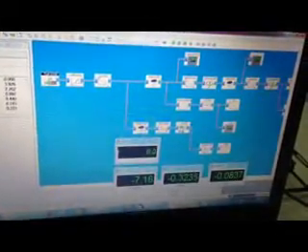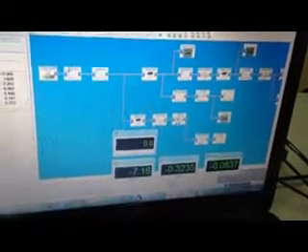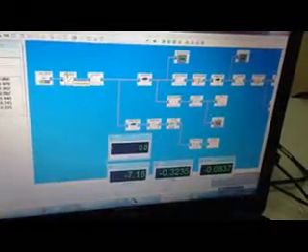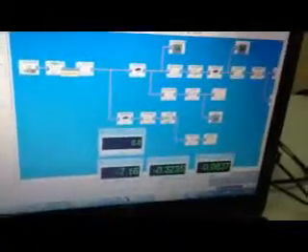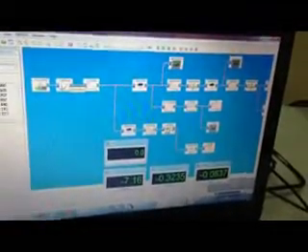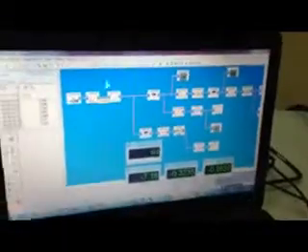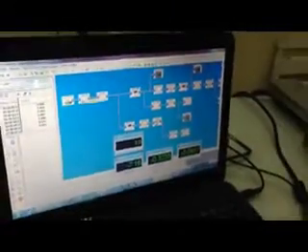Then in this lab, we need to do calibration. This calibration is to convert voltage into displacement. So we do the calculation by some experiment, and then we get the y-intercept and slope values. So we set this value in here.